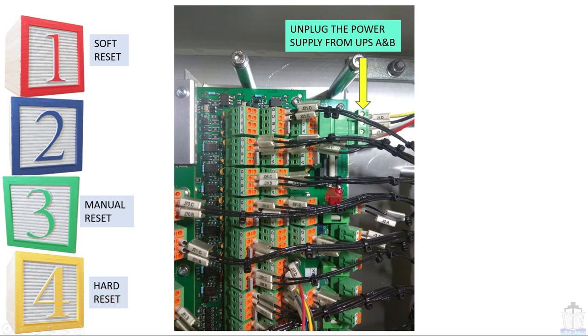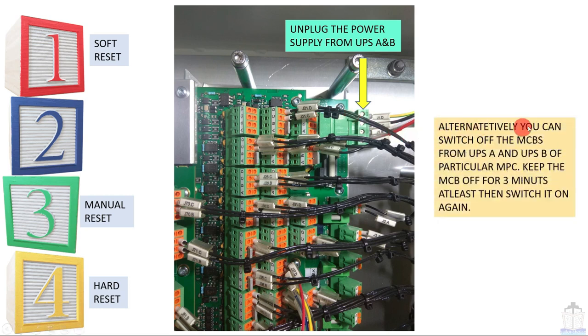Hard reset means you have to take the power supply off from this whole MPC board. That means you are disconnecting the power of the MPC. So unplug the power supply from UPS A and B and keep it for 3 minutes and then reconnect it, and by doing this your MPC will be reset. Alternatively, you can switch off the MCB from UPS A and UPS B of the particular MPC, keep the MPC off for at least 3 minutes, then switch it on again. So there are 4 methods by which we can reset our MPC if it hangs.